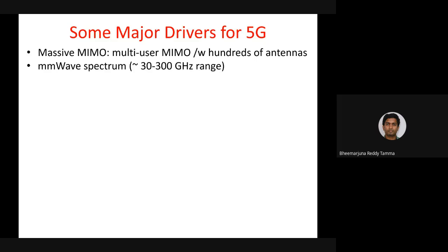But we can also think of deploying Wi-Fi, because Wi-Fi can also have better coverage outdoors compared to indoors. Indoors we have issues related to walls and other things which eat away your signal by 5 dB or 10 dB. That way, when you go outdoor, Wi-Fi could also be a good alternative to 5G, where 5G is going to use millimeter wave.